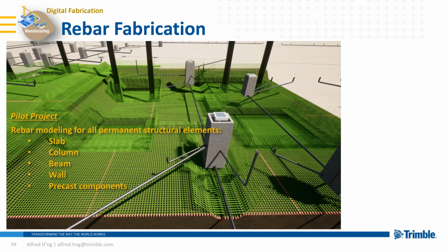In the next few slides, I will show you pictures of the model we created. What you see in the background here is a part of the model. The green is the bottom rebar. Those in black are the temporary king posts, and the strutting system in gray. Inside the model, we merge it all together, and the rebar needs to consider all of this. Besides the rebar detailing, we also need to avoid clashing with all these things. All right, next please.